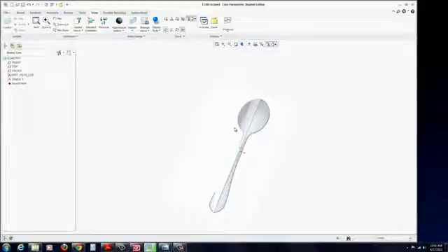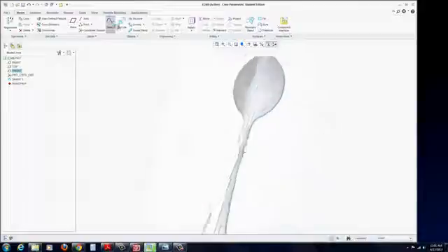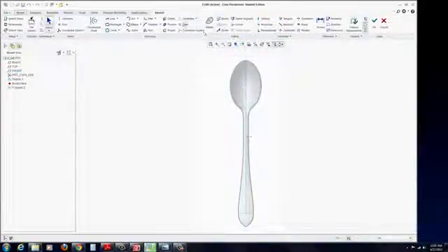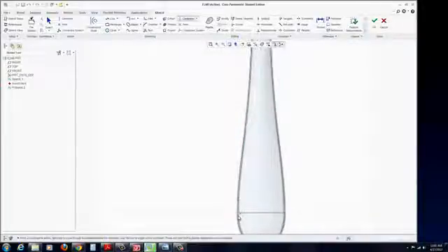We're going to begin by tracing the front view on the left side. So I'm going to select the front plane and go to Model, Start a New Sketch. For the base, because we want a nice smooth transition from this little end of the spoon to the top, right here in alignment, zoom up to this, and draw just a vertical center line, so we could align a tangent to it as we draw our spline.